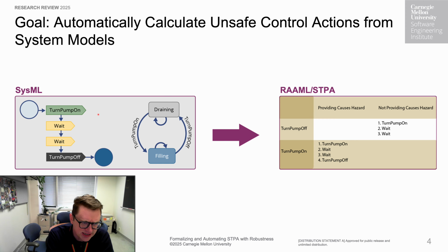In order to fill the tank, we provide instructions to the operator to say, okay, go ahead and turn the pump on, wait, and after you've waited some arbitrary amount of time, and you could specify this. STPA a lot of times has this concept of sort of Goldilocks time, too little, too much, just right, and we follow that here. So you wait some amount of time, and maybe the tank is half full. You wait the same amount of time, now the tank is full. You turn the pump off, and you're good to go, you're done.